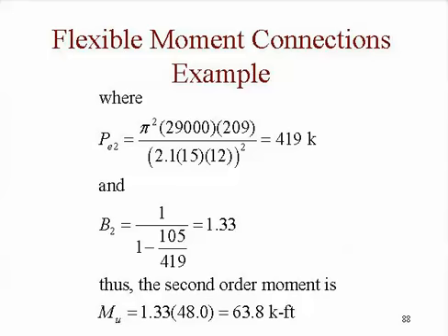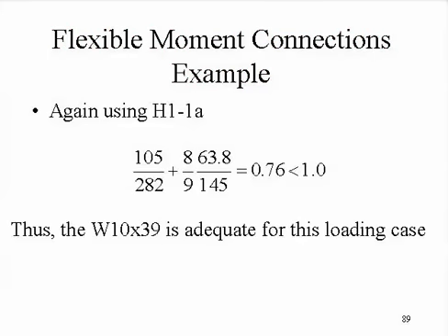We apply that to the moment, go to the interaction equation, and in this case, it's a lower value than we had for the gravity-only combination. So it appears that the W10 by 39 is adequate for this loading case.